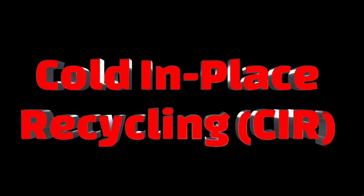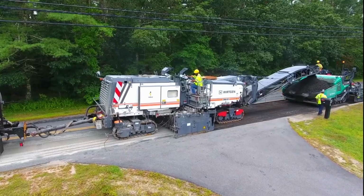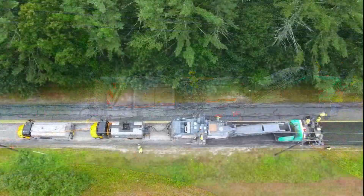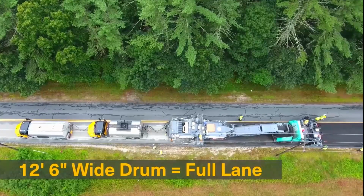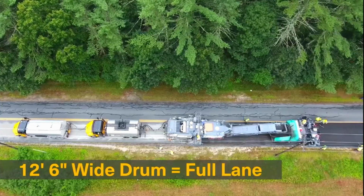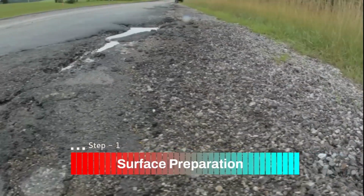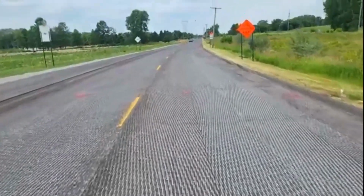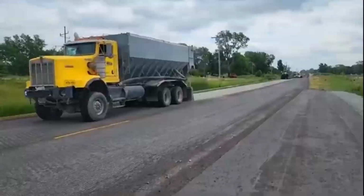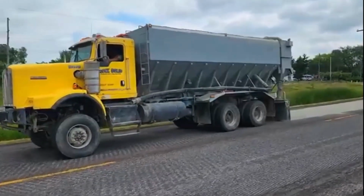The first method, cold-in-place recycling, CIR, step-by-step execution. In cold-in-place recycling, the milling, crushing, mixing, and paving all happen on site using specialized recycling machines. Step 1. Surface preparation. A preliminary survey determines the depth of milling required. The road surface is cleaned to remove dust and debris. If cement stabilization is needed, dry cement is spread on the pavement before milling.